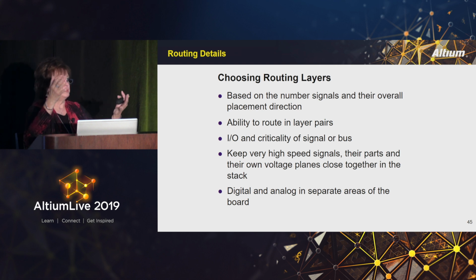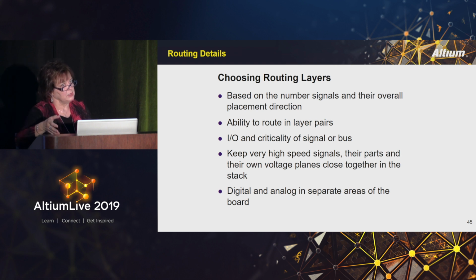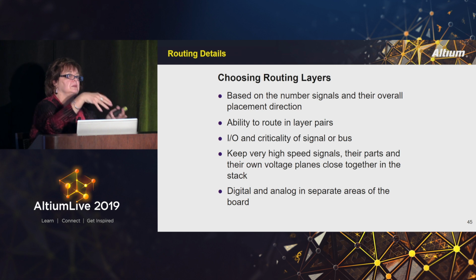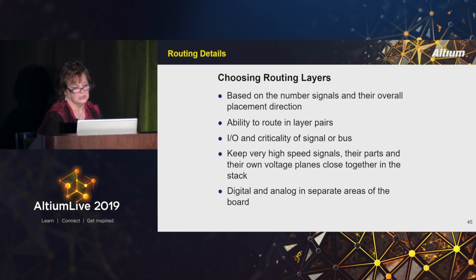If you happen to have a board with a cable that ran next to it in a box in a configuration, and that cable's radiating like crazy, well, it can easily create noise in your board as well if you haven't paid attention and you allowed it to receive energy as an antenna. So be mindful of that as well.